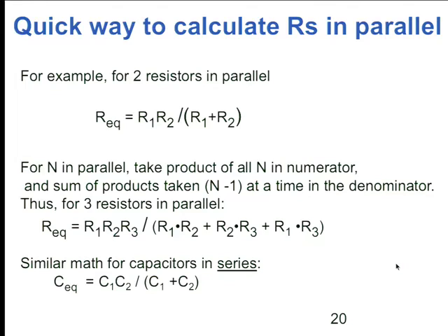See, the thing that's really controlling things is this guy. He's 3,000. So he's really a big resistor blocking the way. So the fact that I made it easier here is not so bad because the resistance here is less, but this big resistor here is holding things up. But let's do in our heads, how much resistance are these two together? Now, if you had to do 1 over 500 plus 1 over 1,000 in your head, you're a better mathematician than I. But we can do it with that little formula here.